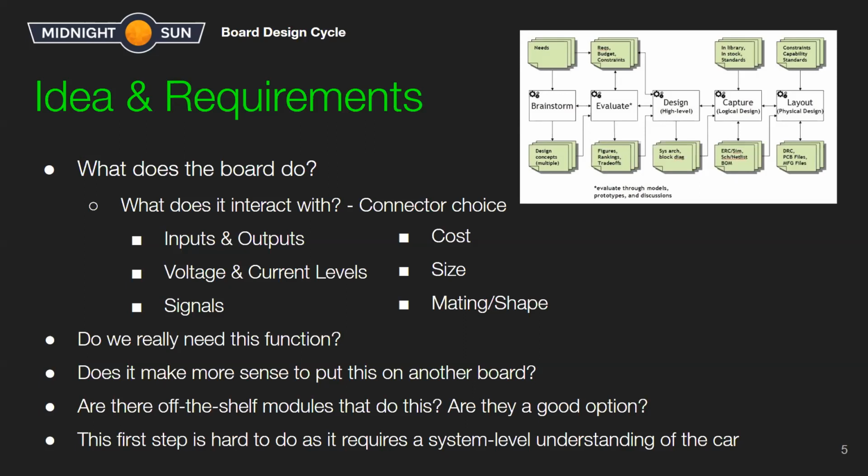And this is the easiest step to simplify the design. Once you start the schematic, once you lay out, then simplifying the design requires you to start over. Not always completely, but if you can simplify it at the start, that's always best. So you should be asking yourself questions like, do we really need this board? Do we really need it to do this thing, or can we do that in a different way? Do we have to hardware debounce the signal, or can we debounce it in firmware? And the trade-offs of those, analyzing that to make the board simpler.